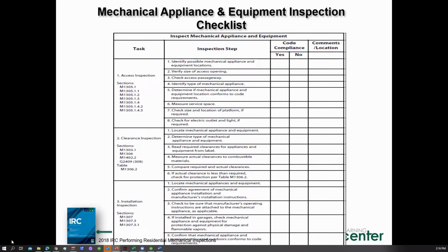Yeah, just a quick question on the combustion air and the venting. I think it was figure 21 you had up here. I'd have to back up to it, but where you had the air coming from the attic, and then a pipe running down within 12 inches of the floor. You mentioned it, and I checked the code section, and sure enough, it says they have to be separate. It's common practice here, as I mentioned, we're involved in inspection of existing housing, so we get a lot of older code installations.